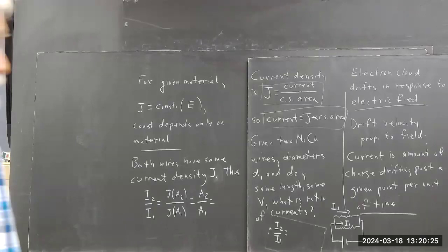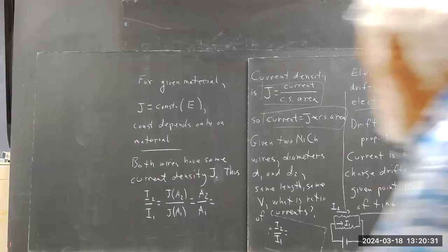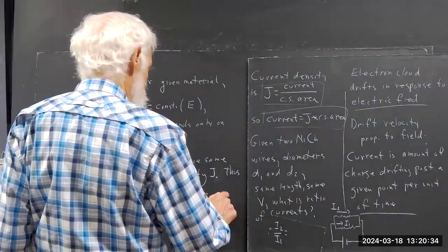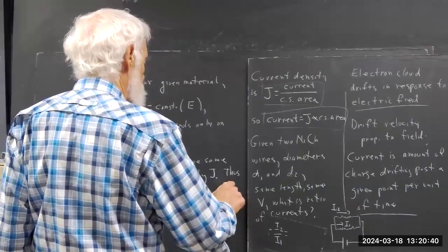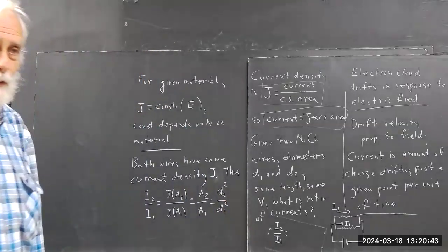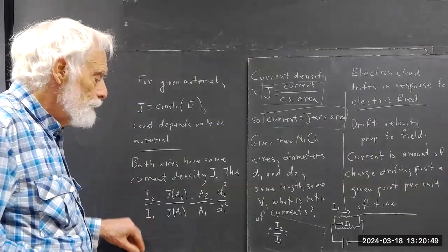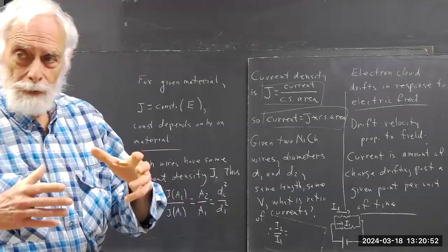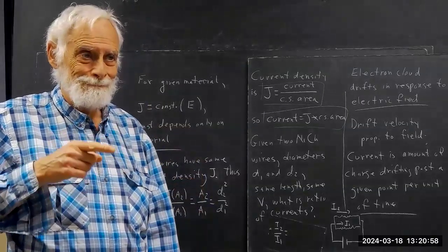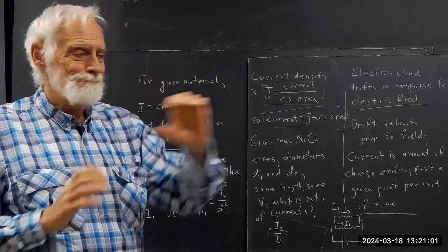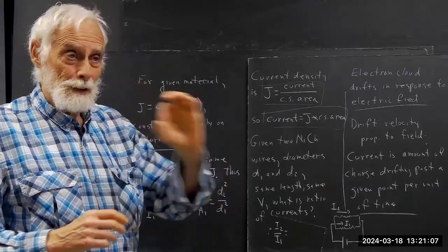So what I've been trying to get us out of here is the idea that the ratio of the areas is D2 squared over D1 squared. It's not the ratio of diameters. We're talking about area, so it's the squared ratio of the diameters. And I think the image people were carrying, because I know one of you, at least in some of your reasoning, was thinking about the surface, like the outside surface of the pipe.